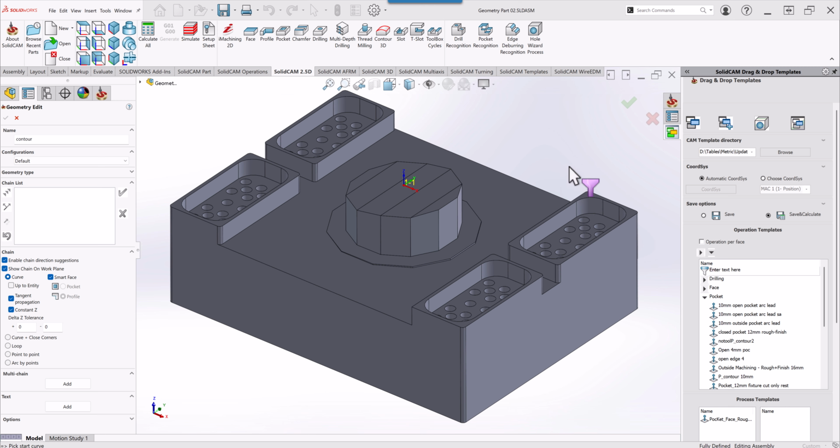In this recording in our series of creating chain geometries, I'd like to create a chain geometry around these edges over here, going all the way around. Now, the issue that we may have is that this floor is not exactly perpendicular to our z-axis. It's slightly tilted, so we don't have a constant z. So picking smart face will not work on this. It would just simply not pick it up.